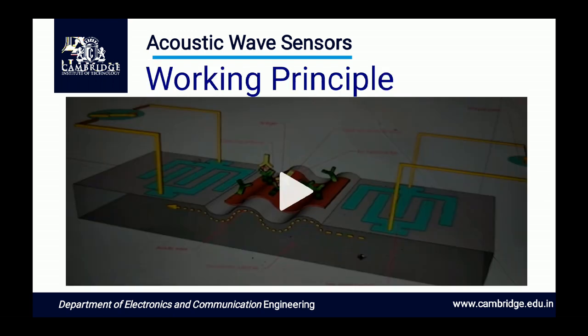Moving to the working principle of an acoustic wave sensor, most modern surface acoustic wave sensors use IDTs to convert an electrical signal into an acoustic wave. When a sinusoidal electrical input is supplied, it creates alternating polarities between the electrodes of the IDT, which creates alternating regions of expansion and compression of the piezoelectric material.